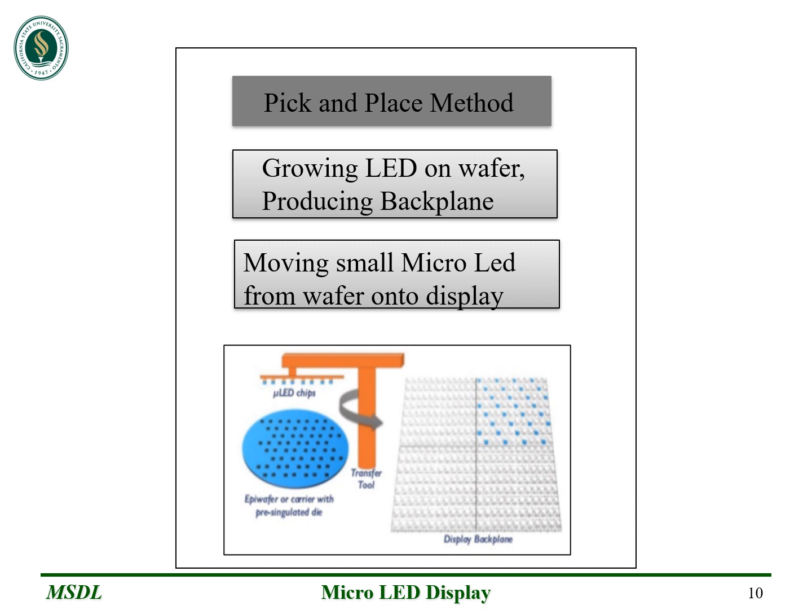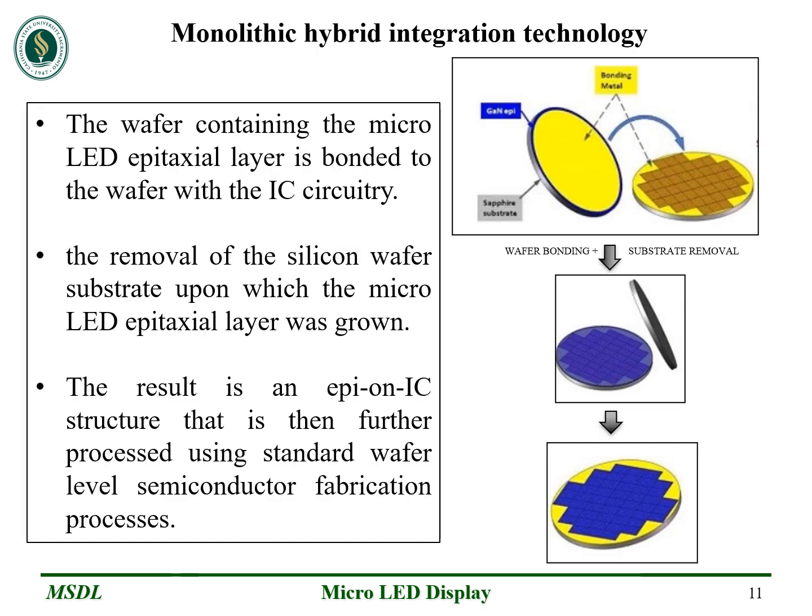Neither of these existing LED transfer methods is sufficient for mass production of larger displays such as TV screens, where millions of micro LEDs are required, because traditional chip bonding and wafer bonding processes don't provide efficient mass transfer for micro LEDs. The alternative monolithic method was introduced to overcome the complications of the pick and place method. Manufacturing times are also very slow and refinement is still needed to improve yield.